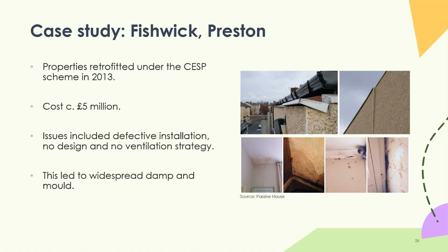You can see in that top left image there, the eaves, where the guttering is above the insulation layer, which is the material with the pebble dash on and that rather horrible plastic finishing moulding that's coming away. Ideally, the eaves where the guttering is would be extended out so that they extend over the level of the insulation.